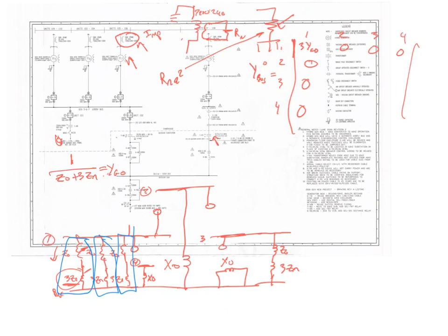How many zero sequence currents do you have flowing through the neutral? 3, right? So you can see in the generator, I actually have these 3 Z0s here. So for this one, we would ignore that 3Zn almost. No, why would you ignore it? Just add it, you just want the representation in the Y bus.